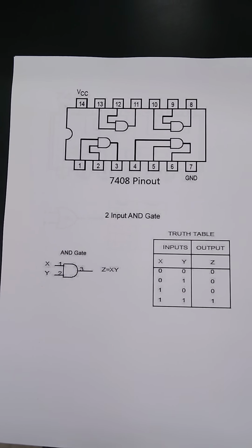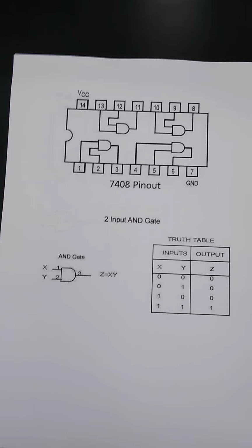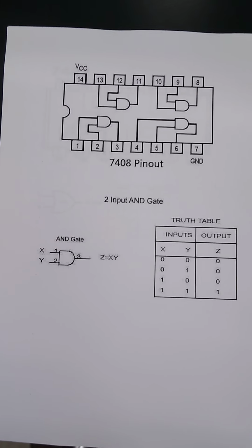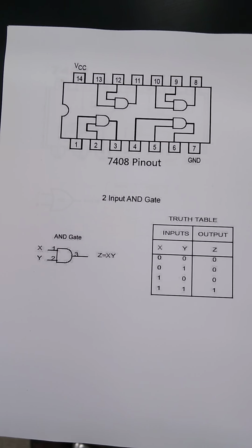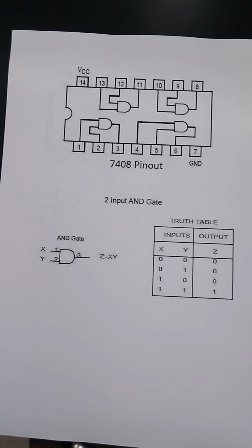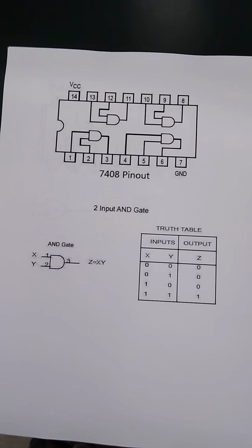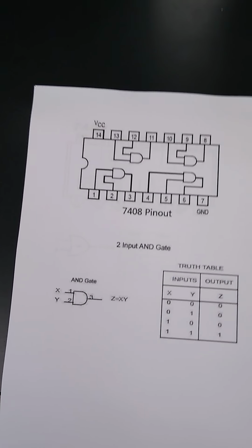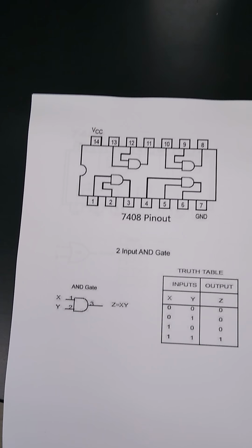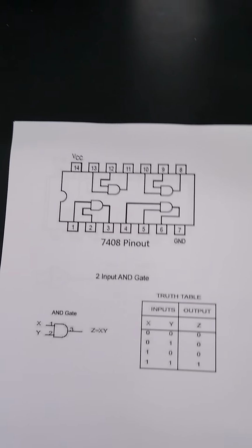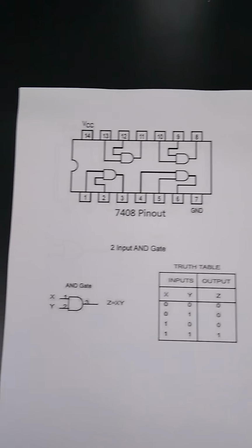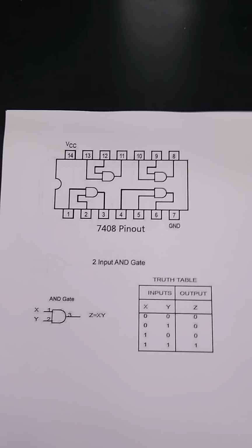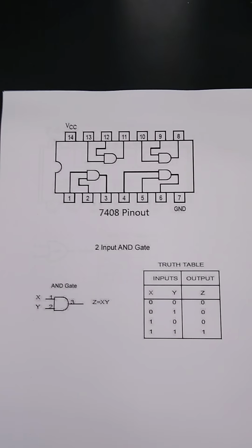The first thing that you need to do with all the integrated circuits: you can see in the figure on top that pin number 14 has the letters V subindex CC. That means this is the pin where you connect the positive of the power supply, 5 volts. And pin 7 has the letters GND, so that means ground. Okay? All the integrated circuits, to operate properly, need to be energized, no matter how many gates you are going to use in your integrated circuit.